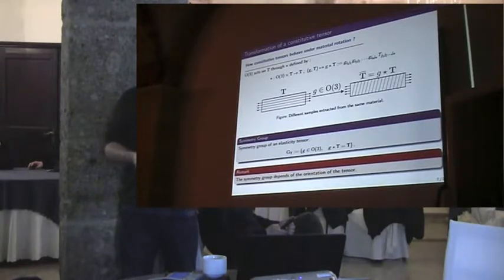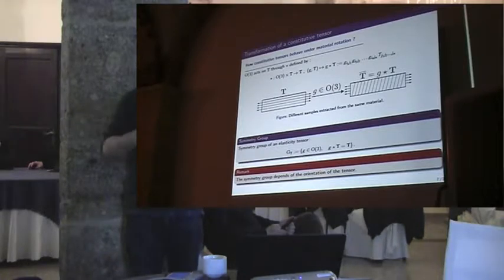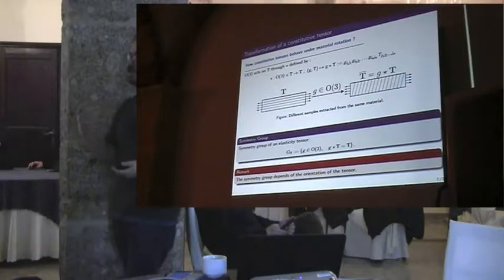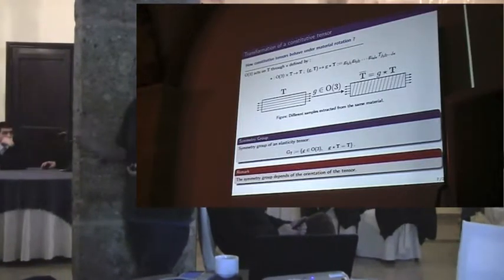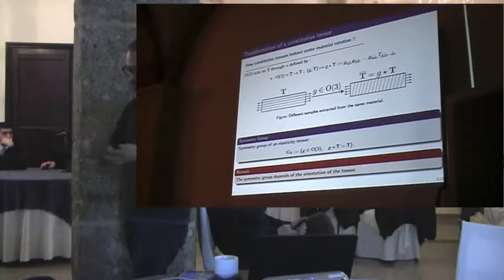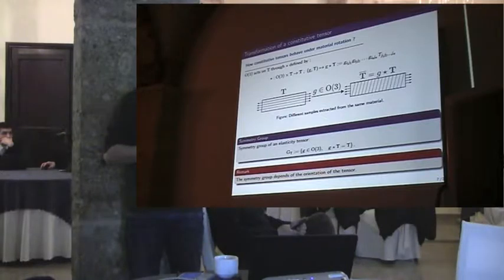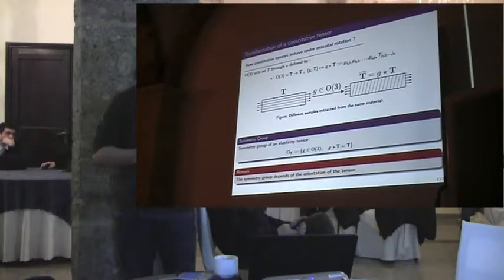So, how does a constitutive tensor behave under material rotation? The rule for transformation in such a case is the tensorial rule. That means that the action of the orthogonal group will act as many times as your tensor has legs. So if I make the rotation, or here it's not strictly the rotation, it's the orthogonal group, and also mirror operation and inversion, it's the complete orthogonal group.